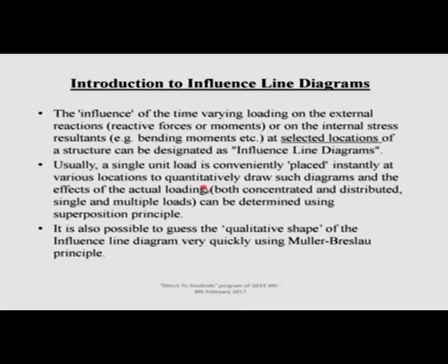and if we deal with a linear structure, and we are interested in the response due to the loading, and the Maxwell superposition theorem and others are valid, then probably it will be judicious to form such diagrams in terms of a unit load and later on do something, so that the effect of the actual loads will be very quickly determined.